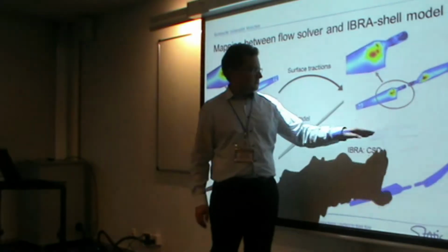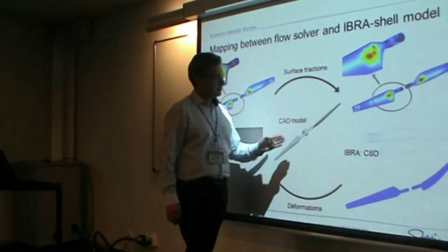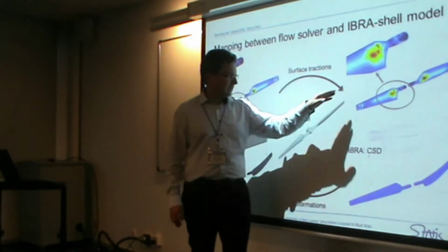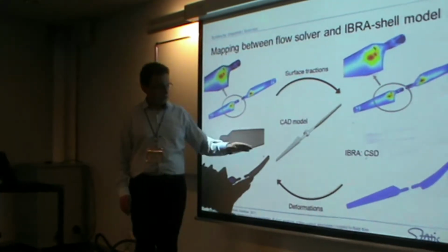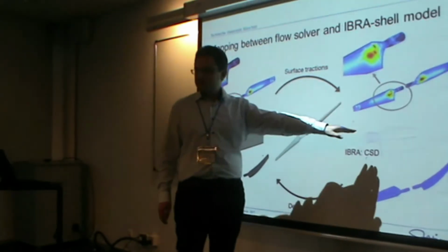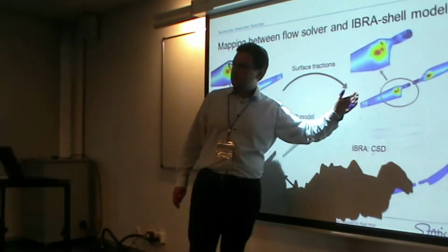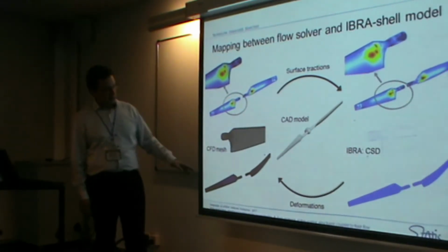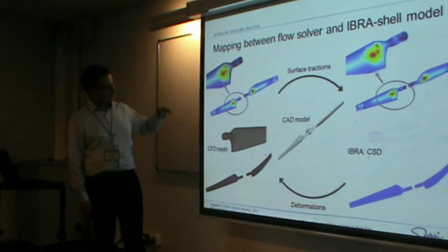Coming back to my initial picture, we have spoken about the requirement of mapping between isogeometric B-Rep analysis, which is at the end something related to the CAD model, typically refined, because the CAD models are typically much more coarse. However, due to the isogeometric approach, the geometry is not changing here, but we have many more degrees of freedom for the deformation state. Here it is just visualized; the animation comes later, but we can skip that.